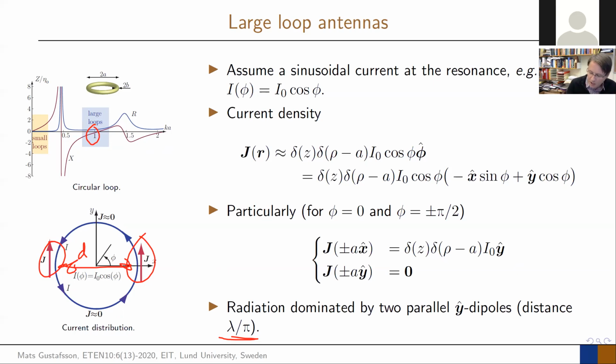And that means that you will have a null in this direction, it's 0. In this direction, you will have some radiation, and it just depends on the distance that sits between them. And if you look in the direction out of the paper, you have maximum radiation, which is then pretty similar to what you had from the patch, but this also radiates downwards. So it radiates both out of the screen and into the screen.